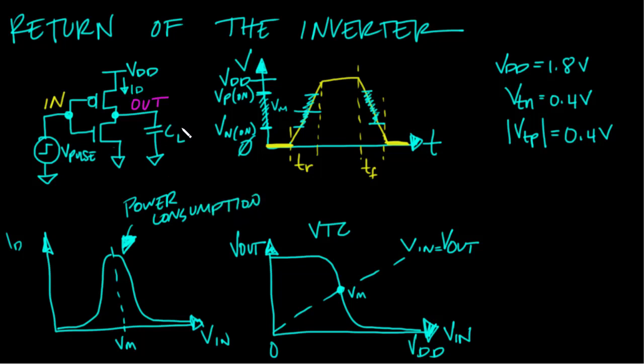And a lot of times they're trying to scavenge power and find ways to reduce the consumption of the devices. And so these types of things, no bueno. So in the real world, you are going to have some rise and fall time on your input signal. You don't want your input voltage to be lingering around this midpoint voltage for a long time. Why don't we go through and think about what would happen if you did have that situation?